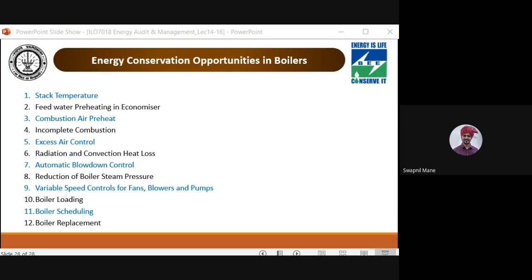A financially attractive reason for replacing an existing boiler is when the boiler has become old and inefficient, or if the boiler is not capable of firing cheaper substitution fuel. For example, let us say there was an oil revolution and furnace oil price dropped, so you purchased a furnace oil fired boiler. Suddenly, after 5 years, you realize that the furnace oil price has increased 3 times, and you now want to shift from furnace oil to a coconut chips fired boiler. The same boiler will not be feasible for use with coconut chips.